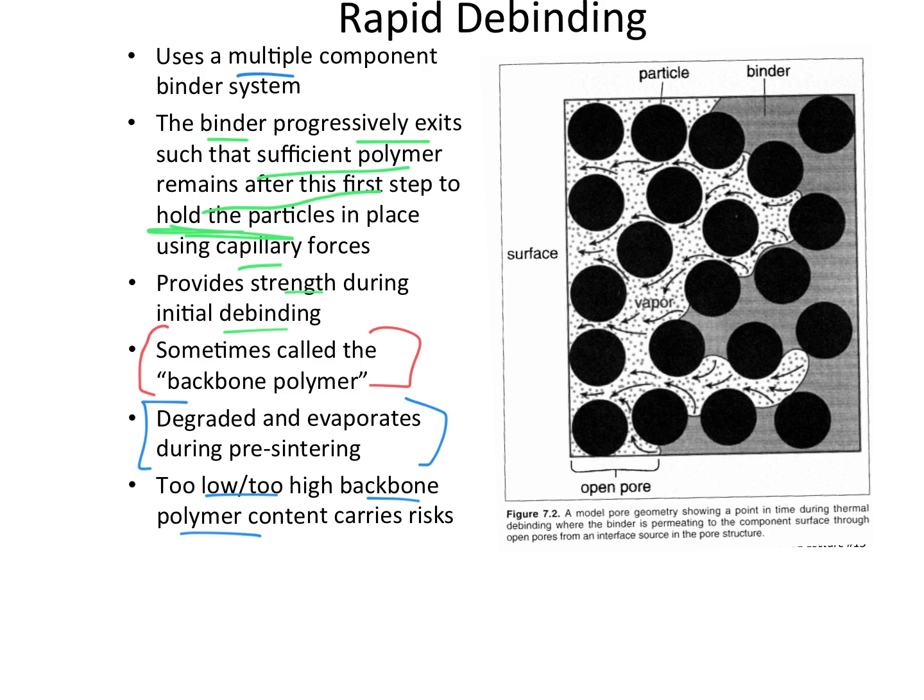oil and water. The two grains that are on both sides of that carbon are literally seeing no strength because carbon is totally incompatible with those alumina and zirconia, you name it. It's a huge weak point. So we have zero tolerance for carbon with ceramics. We have a very high tolerance for carbon with metals. Any questions about that? If that makes sense.